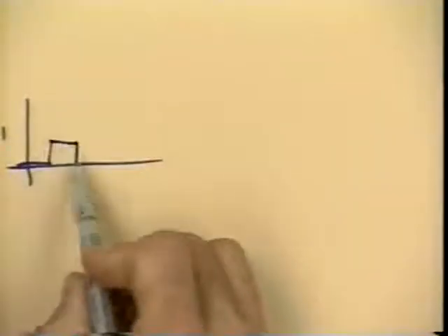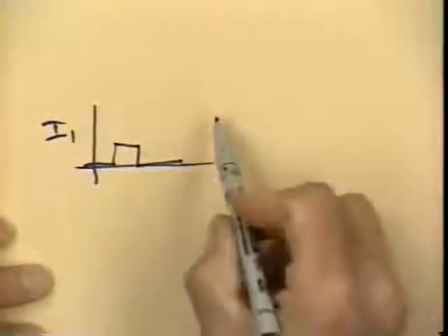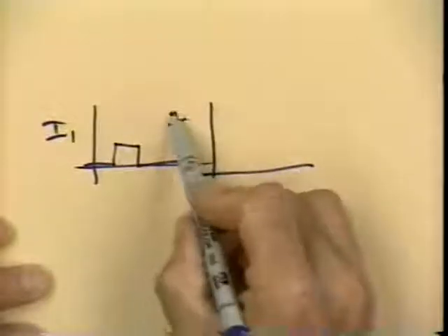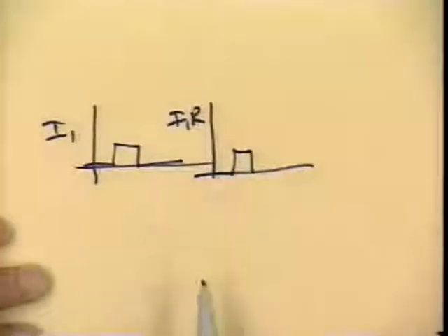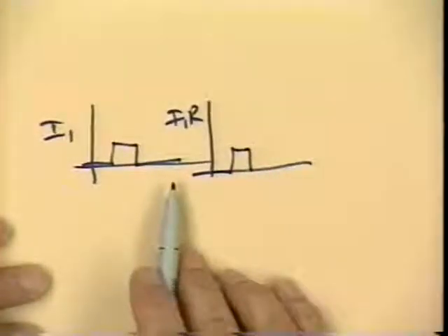So let's say that the current in circuit 1, let's say the current looks like this. I don't need to know exactly what it looks like. It doesn't matter exactly what it looks like as long as I have some idea what this is. If the problem is the resistance problem, if it's I1 times R, then that noise voltage is going to look like a pulse. It's going to look just like the current.